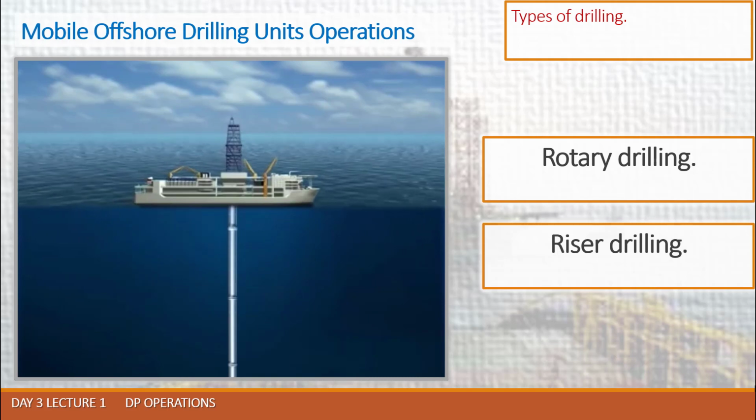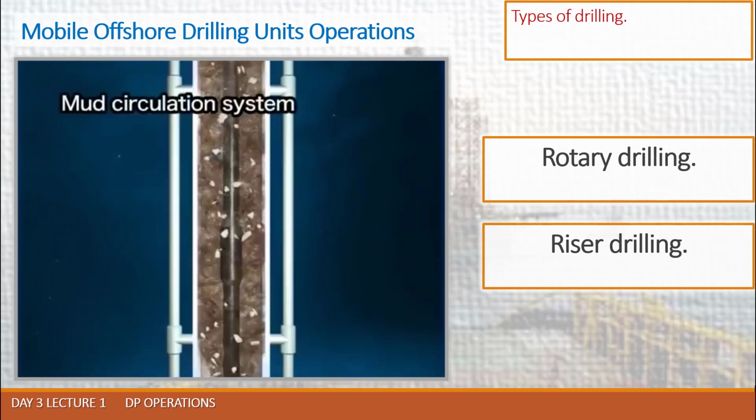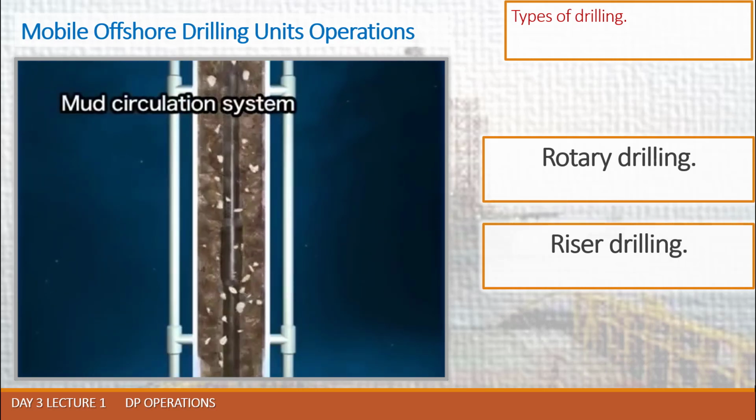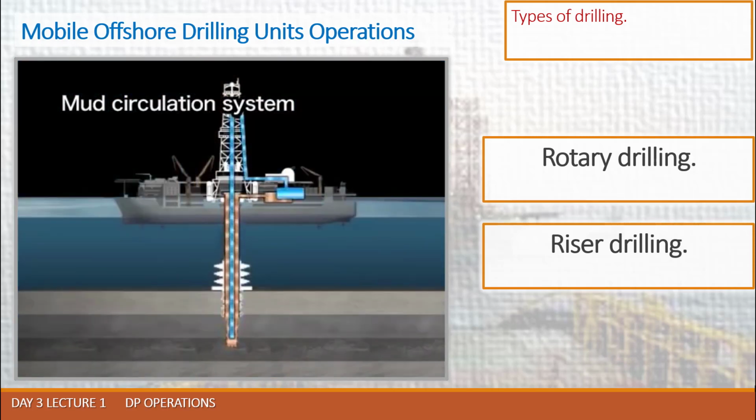For this purpose, the riser pipe is connected all the way from the vessel to the seafloor. The drilling mud sprayed out of the drill bit returns to the vessel through the riser pipe together with the cuttings and is collected and recycled at the vessel.